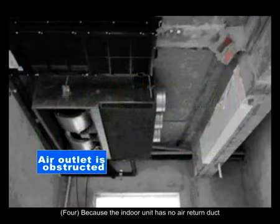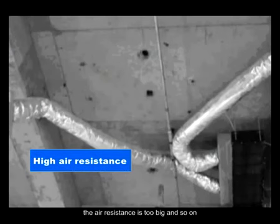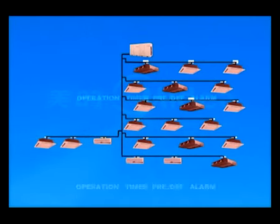4. The indoor unit has no air return duct, the duct leaks wind, the air duct is too long, the air resistance is too big and so on. These can cause the indoor load to become bigger and the performance to become bad.